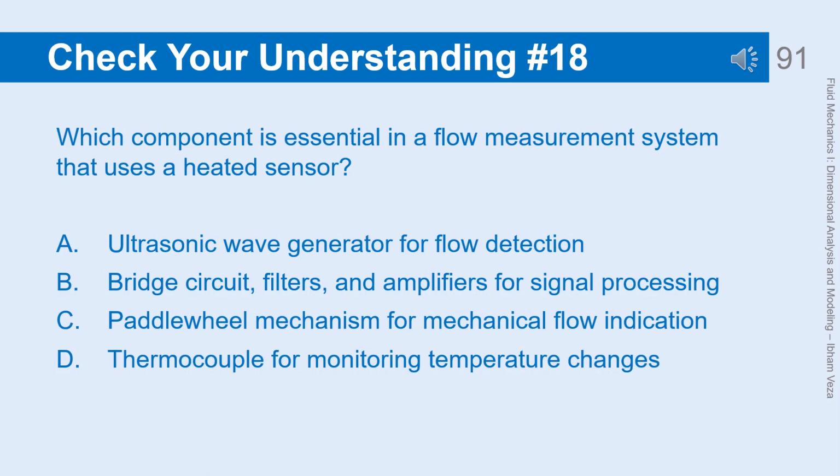Check your understanding number 18. Which component is essential in a flow measurement system that uses a heated sensor? B. Bridge circuit, filters, and amplifiers for signal processing. Explanation. A is incorrect because ultrasonic wave generators are used in non-intrusive ultrasonic flow measurement, not systems with heated sensors.